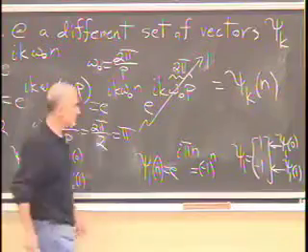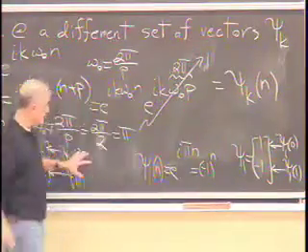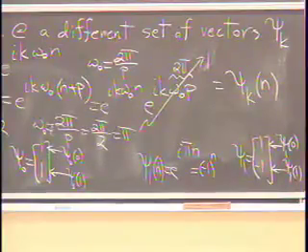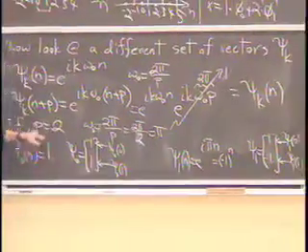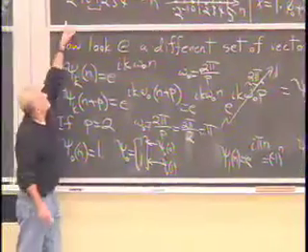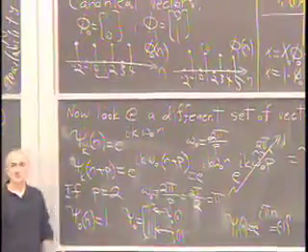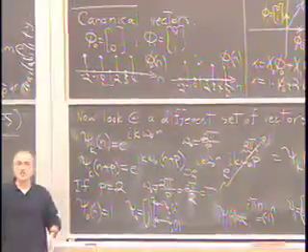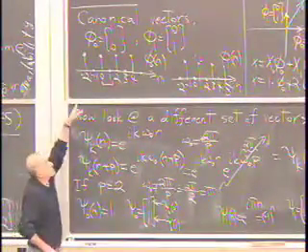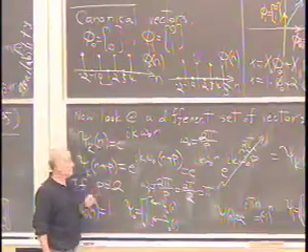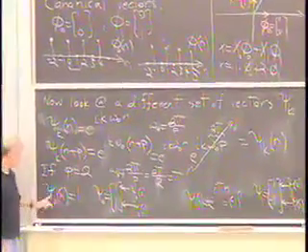So this is essentially our entry into Fourier series. All we're doing when we're talking about Fourier series expansion is changing the vectors that we used, phi_0 and phi_1, that we were very comfortable with. We could decompose any signal in terms of a linear combination of impulses. That's that decomposition. All we're doing now is changing those vectors phi_0 and phi_1 to c_0 and c_1.